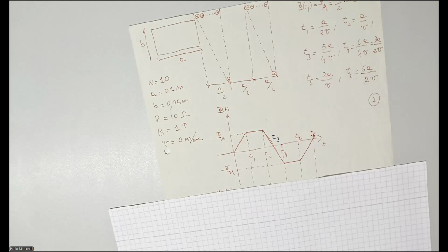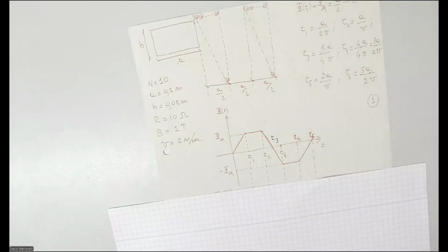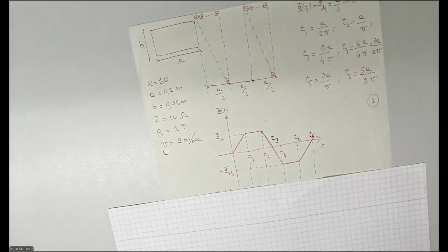Yeah, tell me. Because we have two changes at the same time. We have the change in the negative, but also the change away from the positive. Perfect. Basically, let me consider the right and left parts. In the right part, we include negative flux in the coil. And in the left part, we exclude positive flux. This means we have a double contribution.